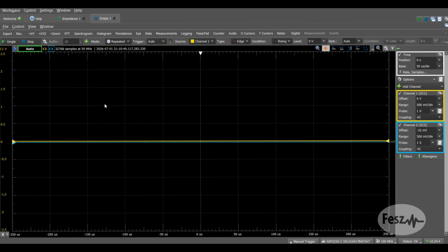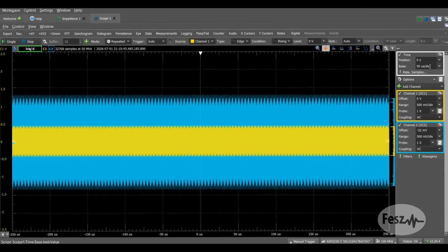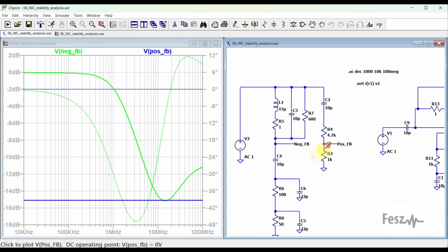And when we remeasure, another successful oscillator. So another thing that I missed when building the model was that the oscilloscope probes have capacitance. If we add, say, 22 picofarads where the probes would be connected, and we check the two lines, well, the negative feedback dips a bit more, just enough to cross the limit.